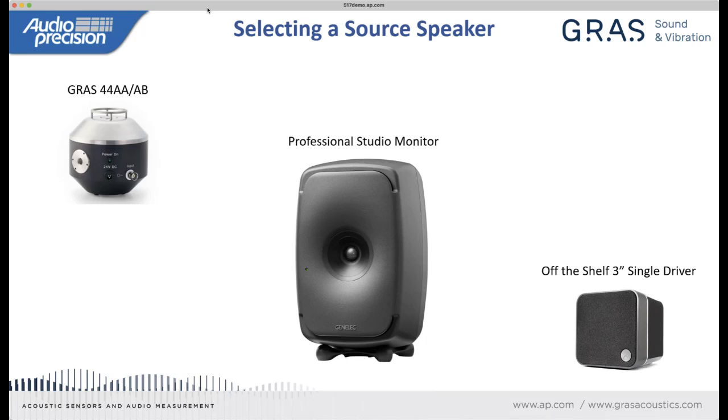Now, in other situations, depending primarily on the frequency range you're required to test over, and also the sound pressure level you need to test over, that might pull you towards using, say, a professional studio monitor, something that has good extension over a wide frequency range, and which, moreover, could potentially be equalized to have a flat frequency response at a given reference location.